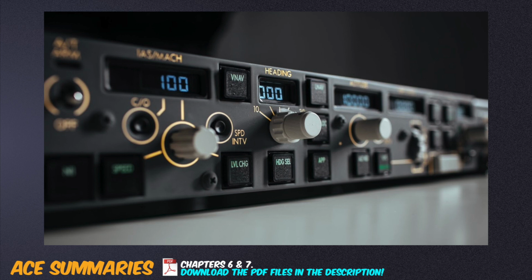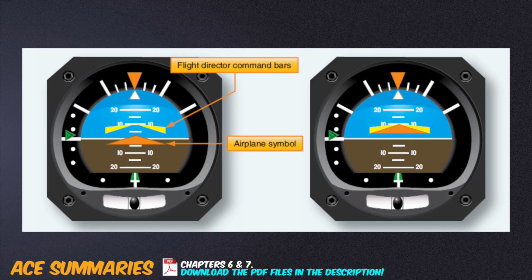Heading, 2. Lateral navigation, 3. VOR/localizer, 4. Altitude hold, 5. Vertical speed, 6. Level change, 7. Vertical navigation, 8. ILS. The flight director uses calculations by the autopilot system to display on the attitude instrument a desired pitch and roll in order to maintain the flight management computer flight path. If the AP is disengaged, the pilot can follow these command bars to fly the autopilot computed path.